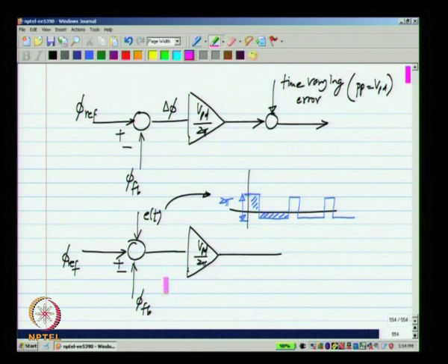Okay. So, the phase detector model consists of this error E of t in addition to the rest, which is normally what we would like the phase detector to be. Okay. And this creates some problems for the phase lock loop, because we see that even if the input is ideally periodic, there are some periodic disturbances created because of the inherent action of the phase detector.